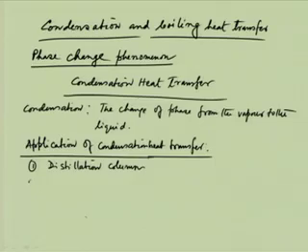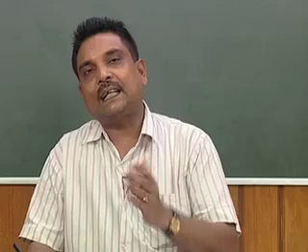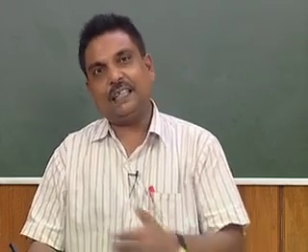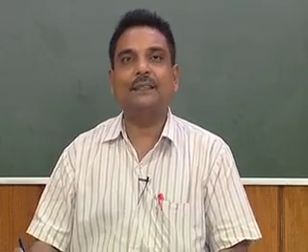Similarly, there are many other examples, like a reactor. From a reactor, we can have some vapor coming out after the reaction, because many reactors operate at a very high temperature, the reactions usually take place at high temperature, and in that case the product can come out in the vapor phase. But if we have to recover the product in the form of liquid, then what we have to do? We have to pass the vapor through a condenser. So, in this case also, this is nothing but a condensation phenomenon taking place, and a heat transfer phenomenon is taking place.